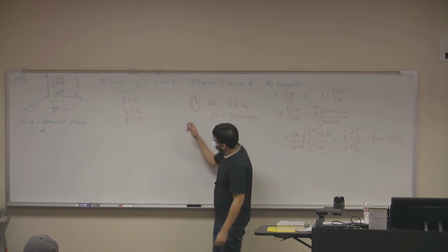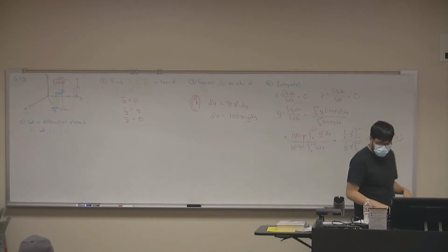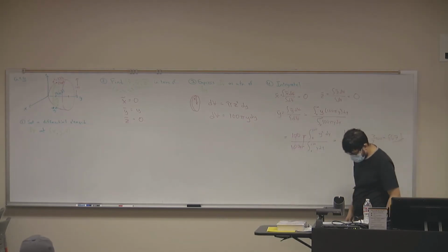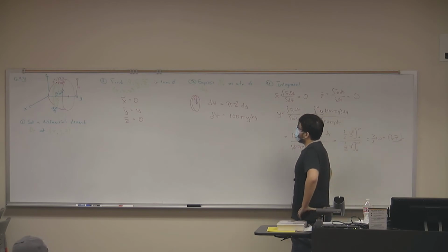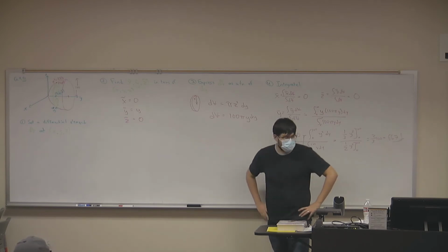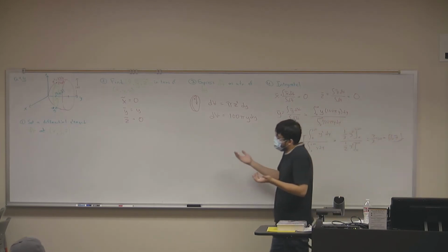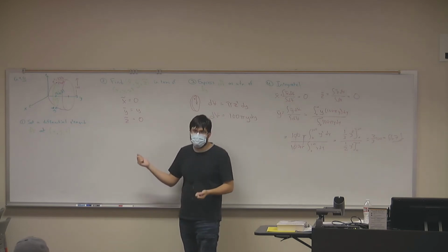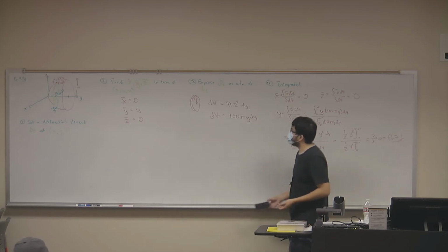Noah, why are x squiggly and z squiggly equal to 0 for that element? When you examine where it's located, on the x-axis, the point of rotation is all about y. And if we're starting from that origin, a circle moving along just the y-axis will be staying at 0 in the z and x. That's right. So we know that our centroid is at the y-axis, and the y-axis is simply a line defined by x equals 0, z equals 0, right? So x squiggly has to equal 0, z squiggly has to equal 0.